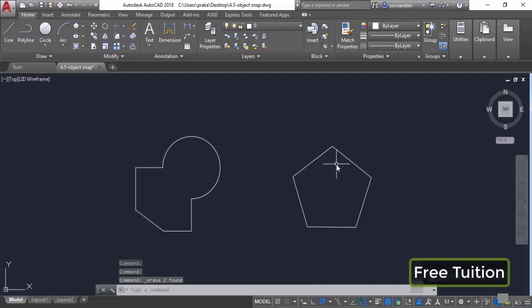And if you want to track your existing snap points, you need to ensure that Object Snap Tracking is on. For now, we have this option off, and now I'll select this line tool. Let's say that we want to make a line by taking the reference of any existing object snap points. For example, here we have this endpoint. Now we want to make a line which is somewhere over here, but which is along this line in the horizontal direction. But when I try to take reference of this endpoint, I don't have any reference here. I'm not able to make any line exactly in this direction unless I make a line here.